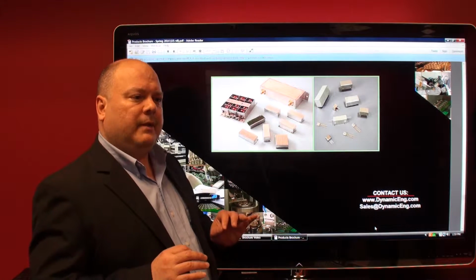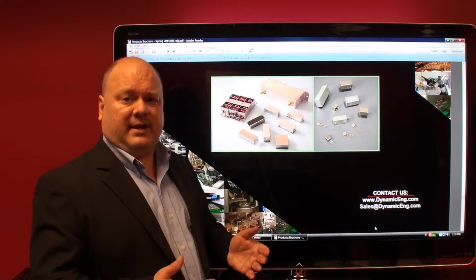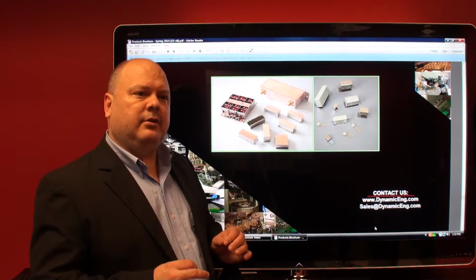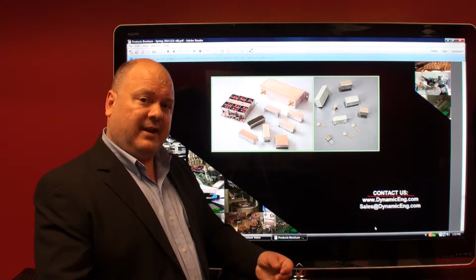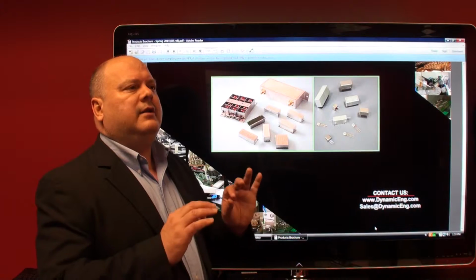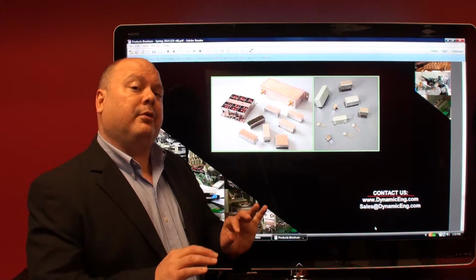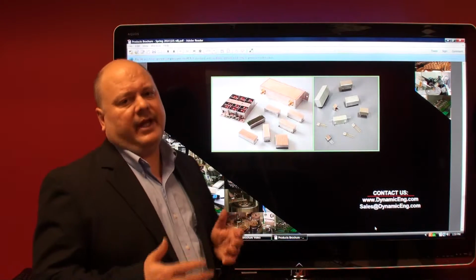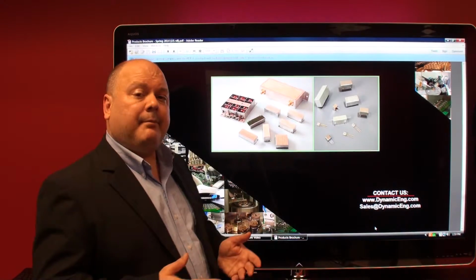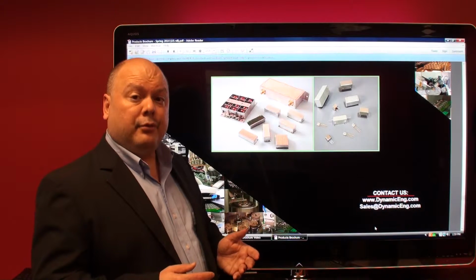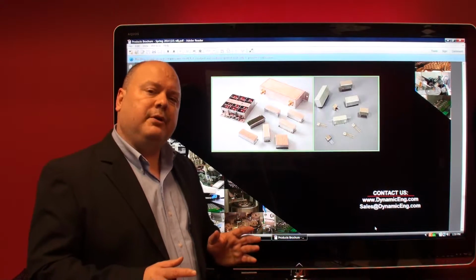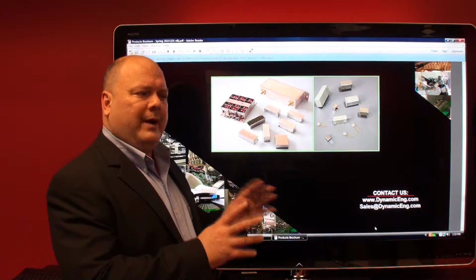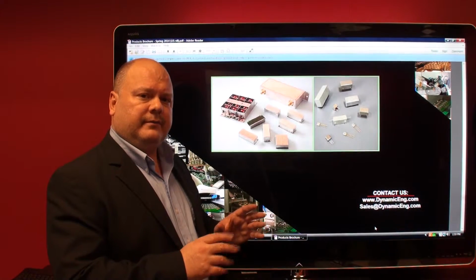Whereas when you are plating, when you are doing the wet processing of the crystals in-house, you have the ability to do the wet process over and over again until you get the right electrical parameter relationships between the crystals. That saves cycle time, that saves scrap, it improves the ultimate distribution of performance of the electrical parameters because you control the wet processing of the crystals.